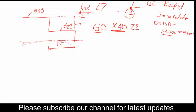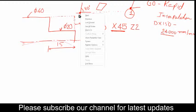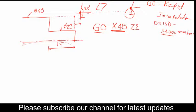Now what do we have to do after that? We have to lower down the tool. We have to lower down the tool to which coordinate? See, this is 40 mm, so we must remove 2 mm in diameter, which means 1 mm depth of cut. So this coordinate in X would be 38.